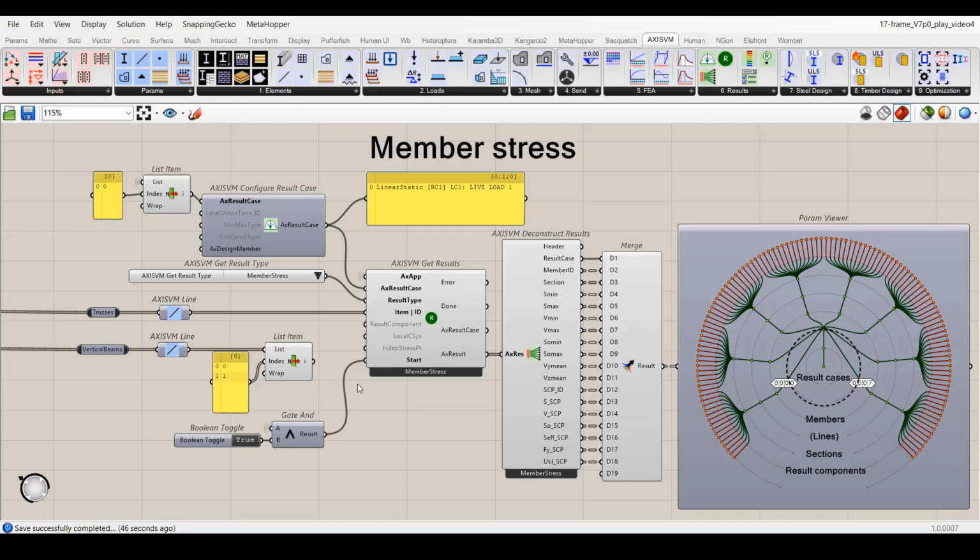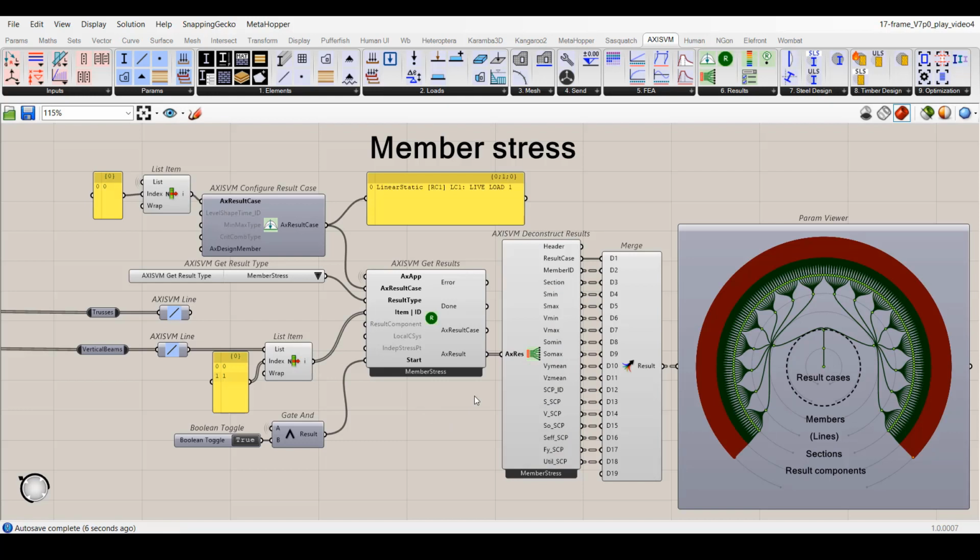If I change the input to 2 beam structural members, I see that both members are split into 8 finite elements in this example, and each finite element has 11 sections now. Compared to the data tree of the member internal forces, it's new that each section has also its own sub-branch, and these are broken into further 15 sub-branches representing the result components. This is required to be able to store the results at each stress calculation point of the sections.